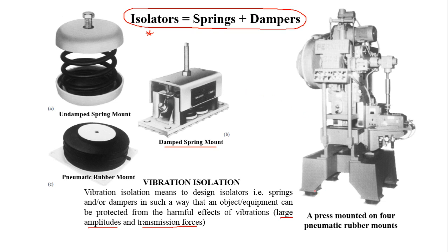And here you can see some pneumatic rubber mounts placed between this machine and its foundation, the floor. So all these kinds of machines that are dynamic need vibration isolation. The prime objective of a vibration isolator is to protect your device, your machine, from harmful effects of vibration.